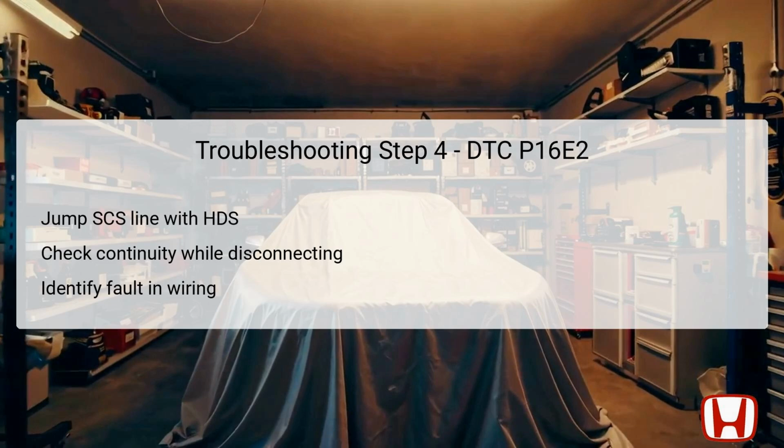If connectivity is interrupted upon disconnecting a specific connector, this indicates the wiring is working correctly, thus highlighting that the disconnected component requires replacement. Conversely, if continuity persists across all checks, the next steps must focus on identifying potential shorts